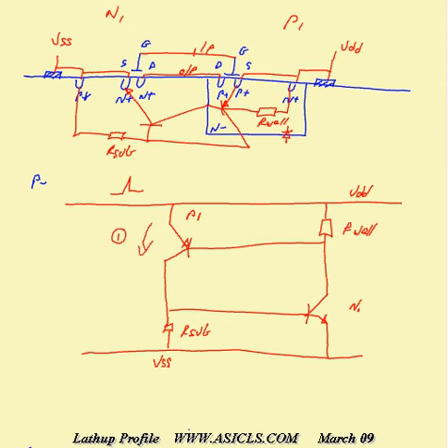We can see that the emitter of P1 becomes forward biased, so P1 switches hard on, so the potential on the top of our sub rises, and so the potential at the base of N1 rises, and so N1 is turned hard on. This means that the base of P1 is effectively connected to VSS, and again it is switched hard on, and so we have latch-up.